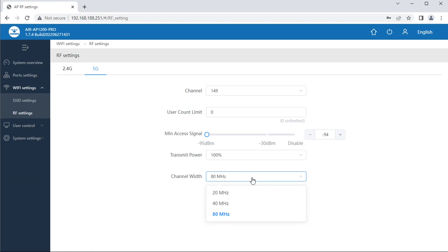So these RF settings provide automatic power and channel adjustment functions with dynamic frequency selection, which makes a channel allocation scheme specified for wireless LAN in 2.4G and 5G Wi-Fi. It is designed to prevent electromagnetic interference, to ensure particular RF detection and management algorithms attain better RF coverage effect. When the signal of one AP is interfered with by strong signals, the AP automatically switches to an appropriate channel to avoid interference by setting auto, while guaranteeing larger distance covered.